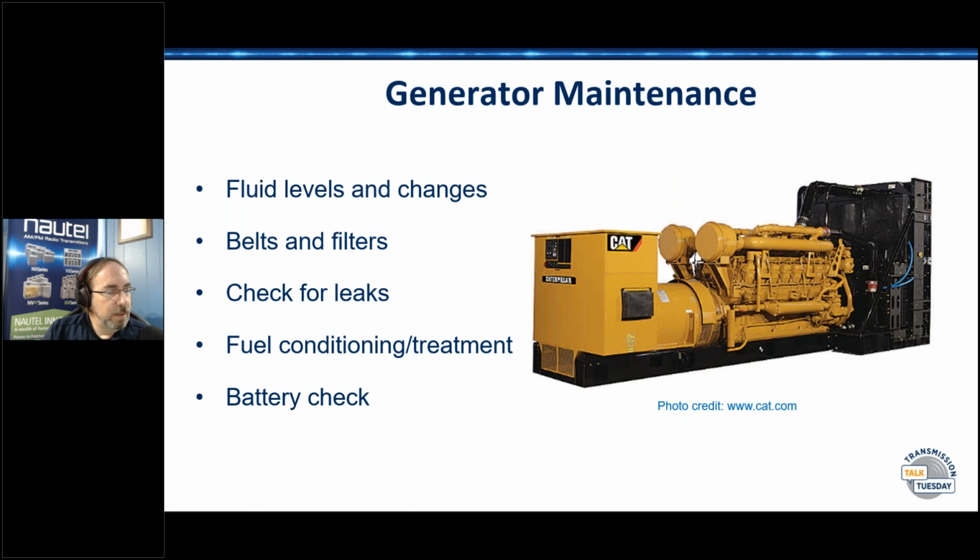Yeah. And redundancy is a big thing for us here at Spirit. I've got 15 transmitter sites that I maintain, and so I carry a spare transmitter in the car in the event that I need to put something in at a moment's notice. For our higher powered stations on the network, I've got a 5 kilowatt transmitter that I can put in and keep the station on the air. For the translators and the lower power stations, I've got smaller transmitters that I normally carry in the car because they're not that heavy and not that big. So: spare transmitter, spare codec, if you're using codecs for all your STLs, even a spare processor.